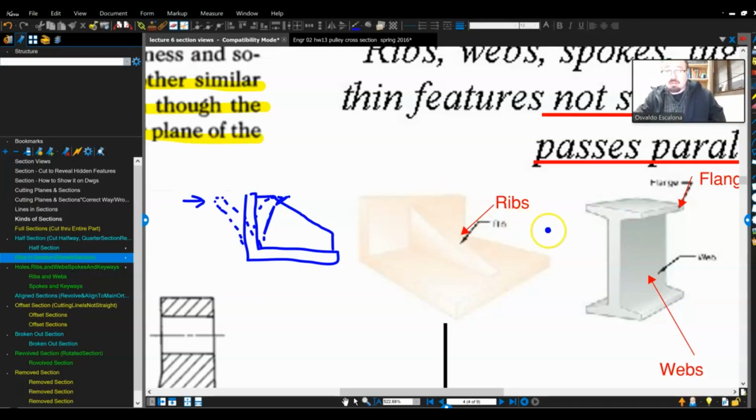The ribs, you usually use when it's already part of your design. For example, for plastic parts that you usually already have a mold for, the ribs are already there. It's all one homogeneous part, not multiple parts like in metal where you have to weld the plate.